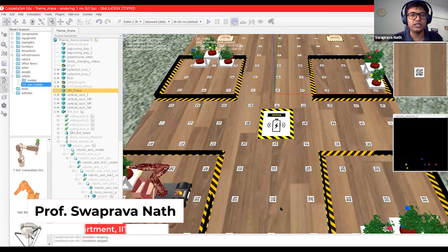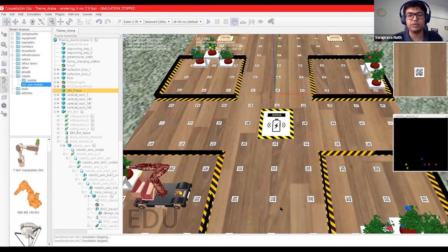Typically, all real-world systems are essentially jittery, and you will have to first model how this robot moves. Maybe you can create a noise model, and you can design according to that. Maybe a window around it, a circle around it, through which it should pass. I mean, the whole circle. You don't really just take care of the size of the robot, rather you take care of that circle around that robot. The entire circle has to pass through the entry or exit.